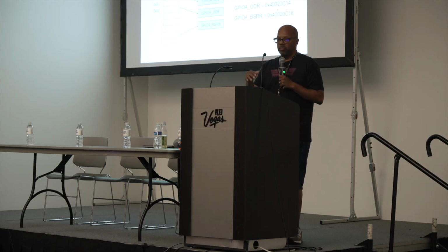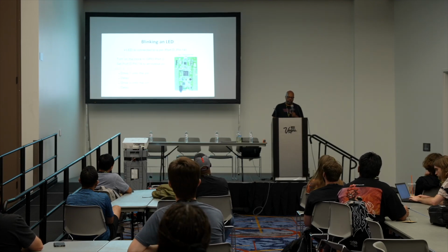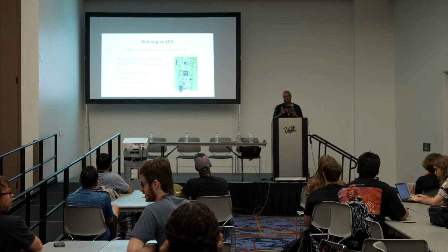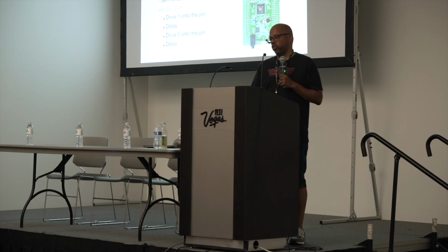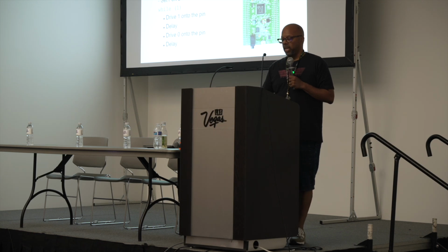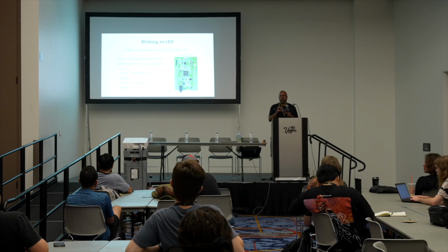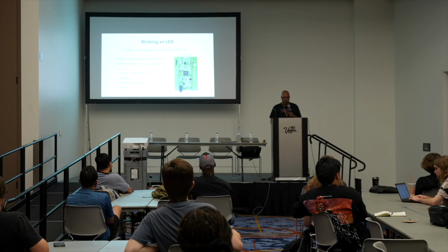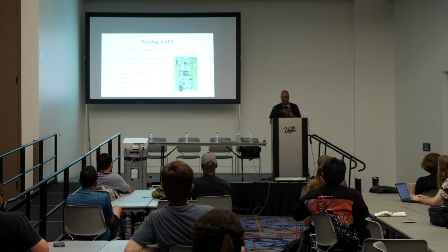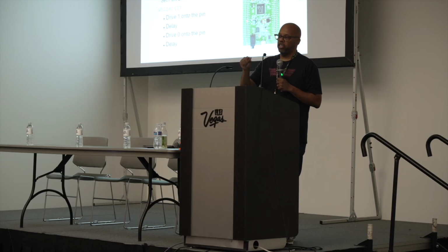But anyway. All right. So, blinking an LED. This is the one I'm going to use in class: an ST Microelectronics board. This is the main microcontroller, and this is a USB interface used for loading. Say I want to blink an LED. Now on this board, I should mention there's a difference between the microcontroller and the board. The microcontroller is this chip right here; it has its data sheet and all that. The board is this whole thing which has the microcontroller on it.